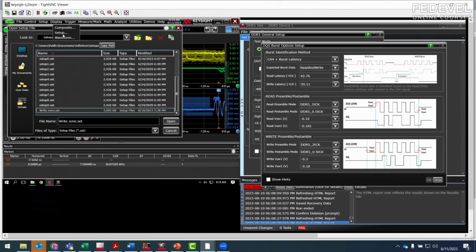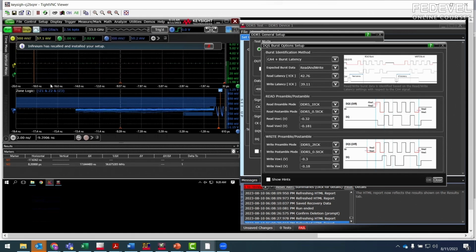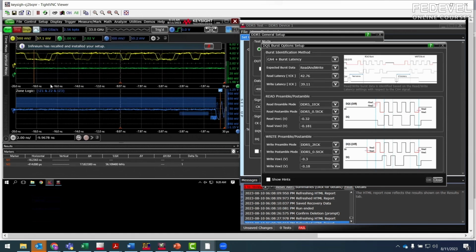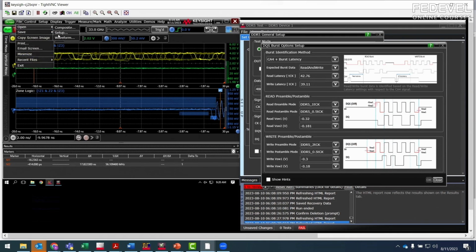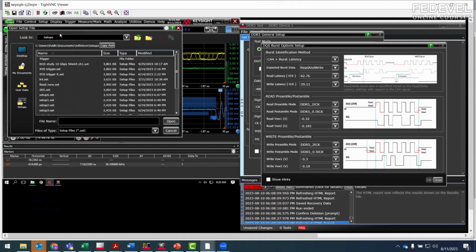This is super useful, because I would probably be trying to find these numbers from a datasheet or memory controller or something, but it's much better just to measure it this way, then you will be sure what the settings actually are. Okay, now here's another hint. Notice that based on the settings that I have, the write should be, I think it's important.